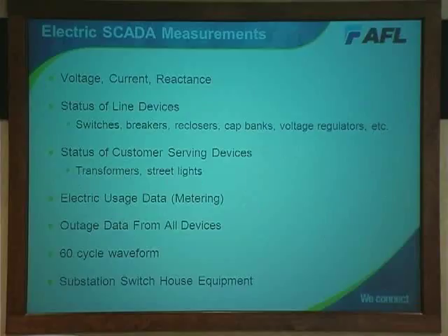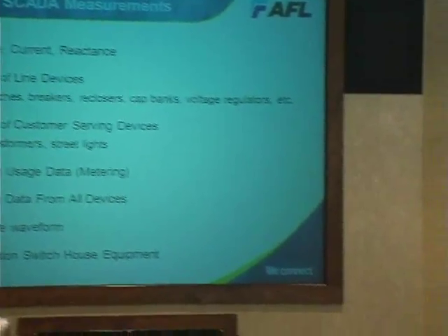All right, so here's a few examples. I asked you earlier what you thought they got. So we'll see how many of these we mentioned earlier. Kind of basic things I know we did mention. We want to know what the voltage is. We want to know what the current is. We want to know what the reactance or capacitance is. We want to know about all these devices out there, these switches and breakers and reclosers. We want to know, are they open? Are they closed? Are they working? Are they not? Are the capacitor banks online, offline? We've got to know all of that.